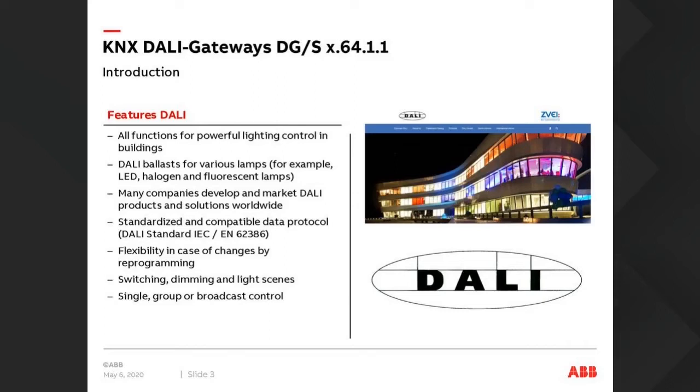So what happened over time was that manufacturers of DALI devices tended to add features and wander from the scope. For people like us who are looking to control DALI lights, it gave a lot of problems, because within the DALI drivers and ballasts they were adding features that we couldn't control and had no idea what they were doing. We were always playing catch up. So the DALI Association, in its wisdom, came up with the new DALI 2 standard, which has just been enacted. Now, to comply with DALI 2, your devices must comply with the rules and regulations.